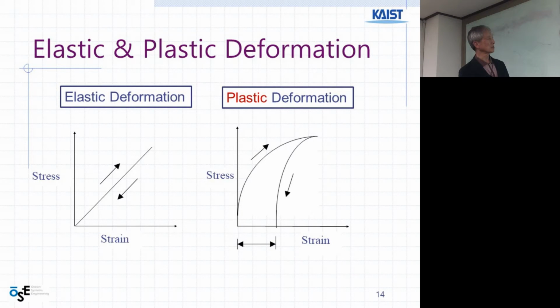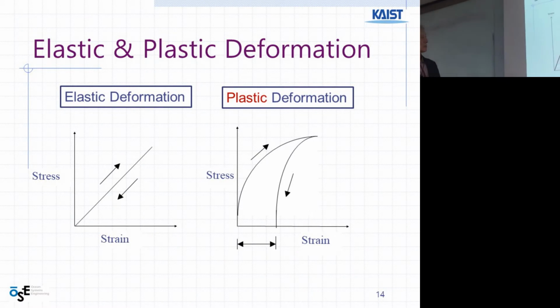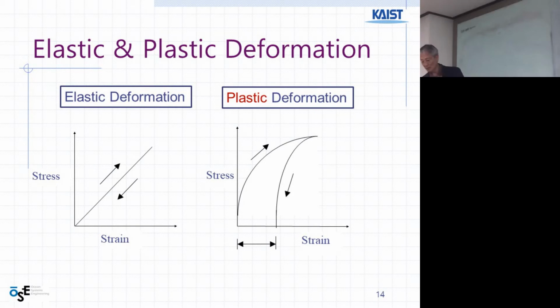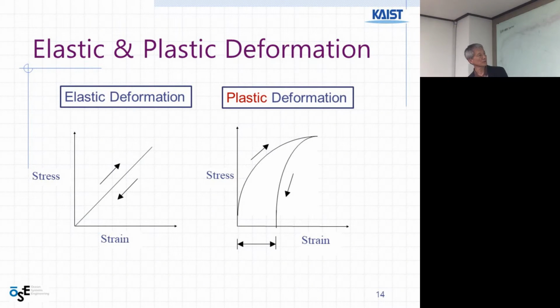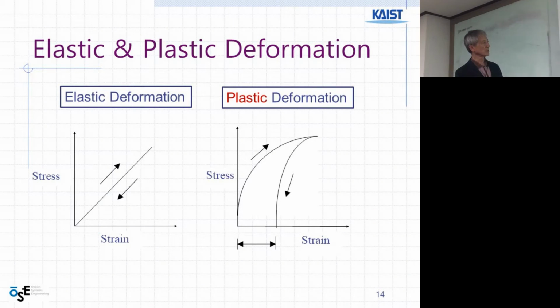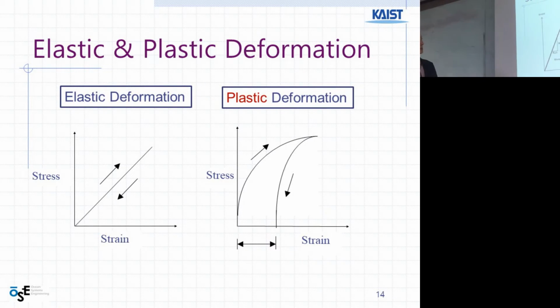And then the stress-strain diagram. This is the linear, elastic deformation region. It is elastic and linear up to the yield strength, and then it goes further to the ultimate strength, and then fracture, and necking and strain hardening, Young's modulus.